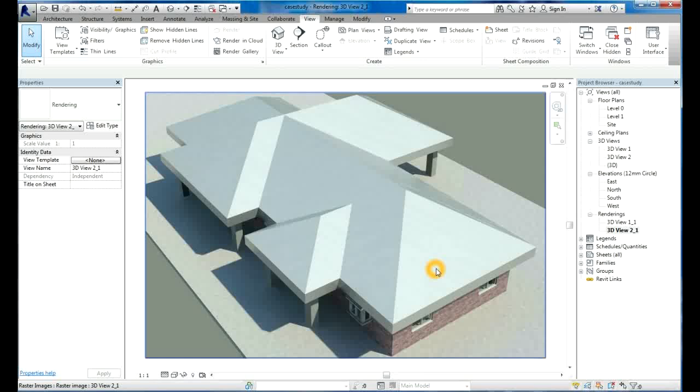We looked at levels, we looked at wall types, we then went on to internal, external walls. We looked at putting columns in, we did the doors, we put the windows in, then we put the roof in, looked at the site, how we might do that, which is floor functions again, and then we put in the components within the building, from the furniture to the plumbing.